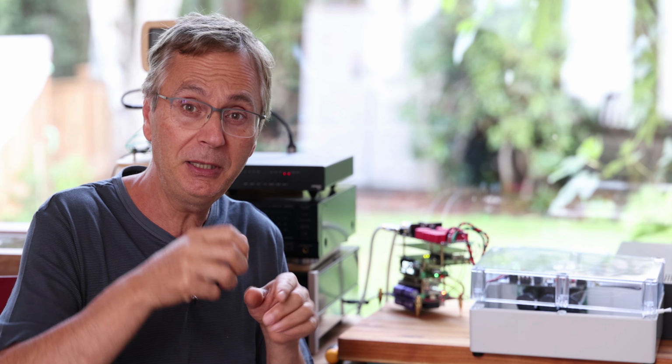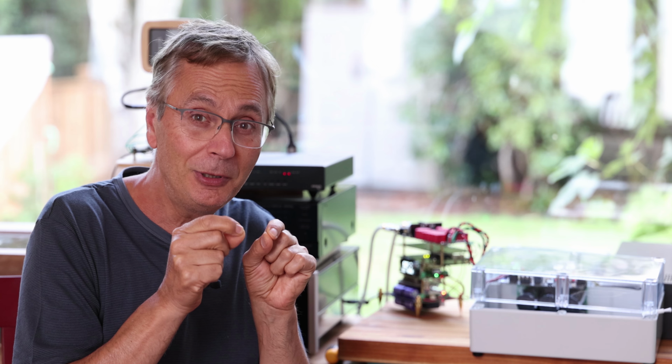If you are building the DAC, make sure you watch the build video, especially the beginning. There are a few things you need to know. They're a must if you are building this, so you don't mess things up. Also, the UFL connectors are very tricky. They only have one positive and three negative, so you have to make sure it's oriented properly. Make sure you use a magnifier. At first it looks all square, but under a magnifier you can see a couple of little notches on one end, and then you know which side is positive.